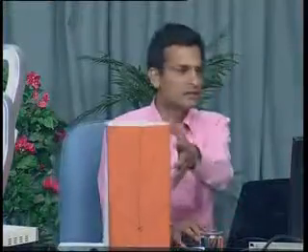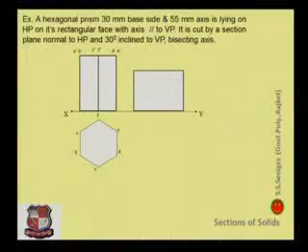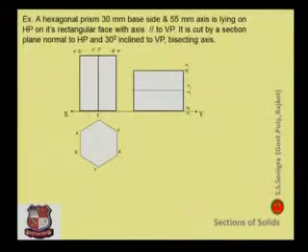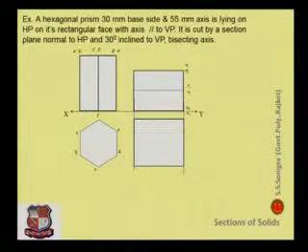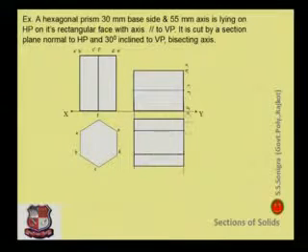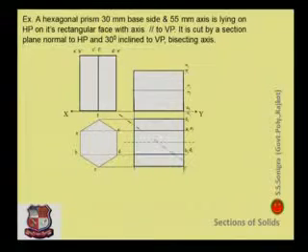So here, after drawing this hexagon like this, draw its top view and front view, and tilt this front view like this. Make it horizontal. Take projections from the top view, horizontal lines from the front view, and draw its top view as well, like this. So we have drawn the front view and top view. Now it is given that it is cut by some cutting plane.